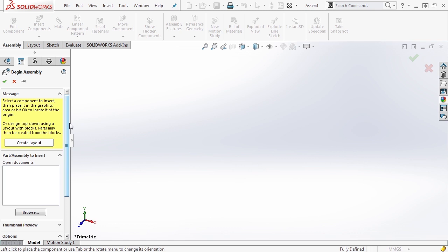There are several other ways that we can do it. But what I really want to focus on is what an assembly is. Now, an assembly is essentially an empty file. That's not universally true, but essentially it's an empty file that is looking for components. It's looking for references. So if you think about creating a hyperlink to a website, you don't have that website in your hyperlink. You're really just redirecting the user, when they click on it, to go to a certain website. And an assembly is a very similar sort of aspect. It doesn't contain the part itself, it contains a link to the part.